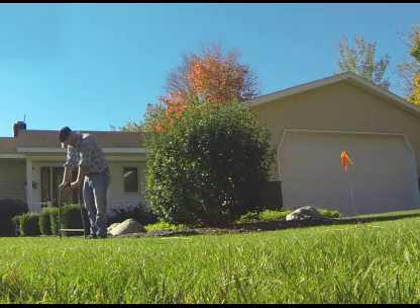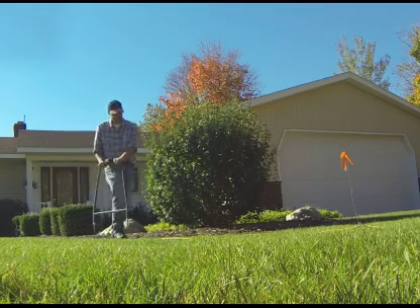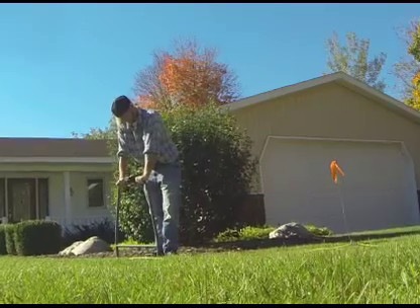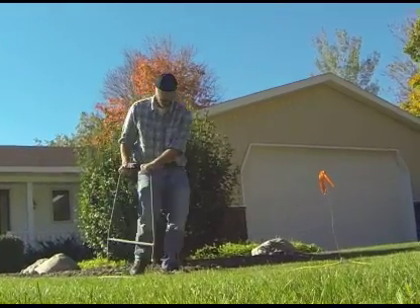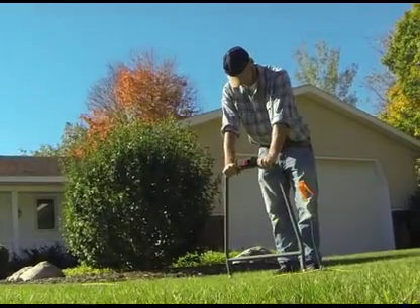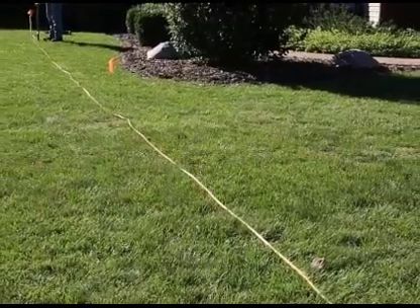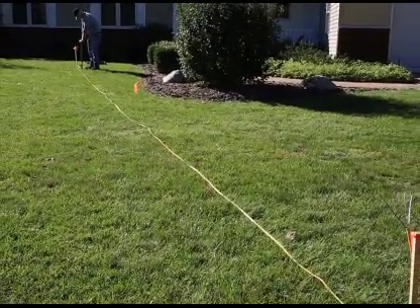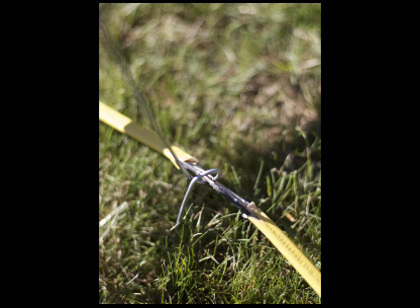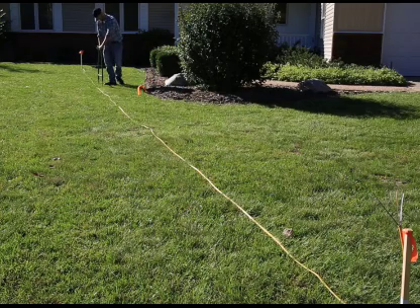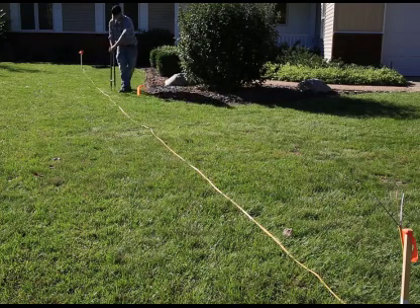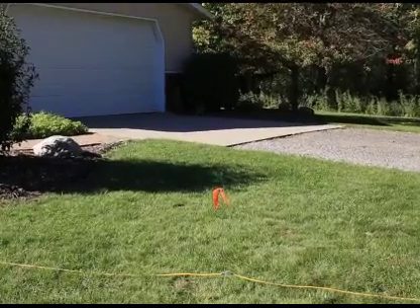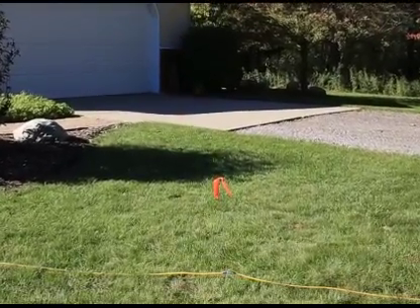The GFL3000 is designed to pinpoint the exact location of a ground fault in a cable. The GFL3000 is not intended to locate the entire path of a cable. To effectively pinpoint the location of a fault using the GFL3000, the path of the cable must be previously determined and the wire must be in direct contact with the earth. To demonstrate that the path of the wire has been previously determined, the wire has been placed above ground. The fault is illustrated with a flag for further clarity.